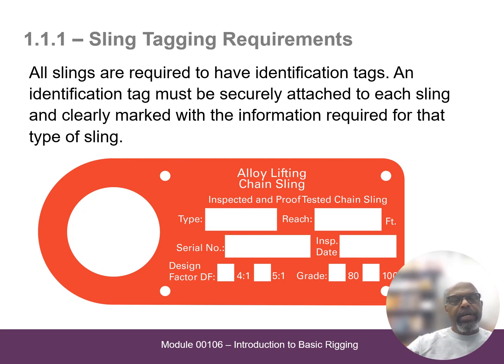Alrighty, when we're looking at any type of sling or any type of lifting device, it is designed to handle up to a certain load, in other words, a certain weight capacity, and that needs to be always visible. Always. If it's not visible, you need to get rid of that lifting device, because each time you lift something, you need to know exactly what it's rated for.